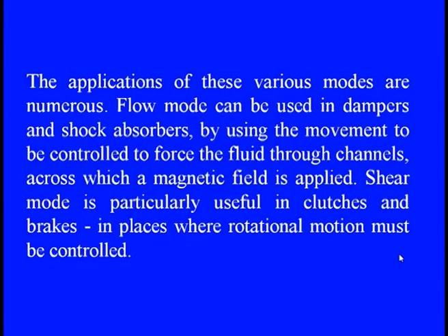So flow mode can be used in dampers and shock absorbers, where the movement is controlled by the force and flow through the channels across which the magnetic field is applied. This is a very smooth part in which we just want to absorb or dampen out the vibration. This is one of the perfect places to apply it.